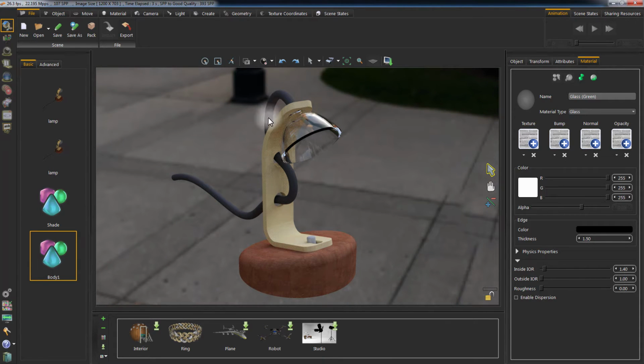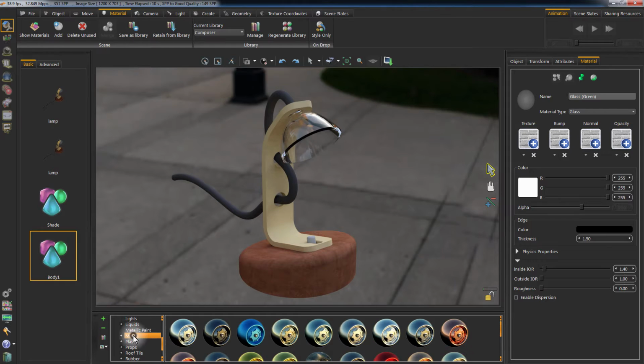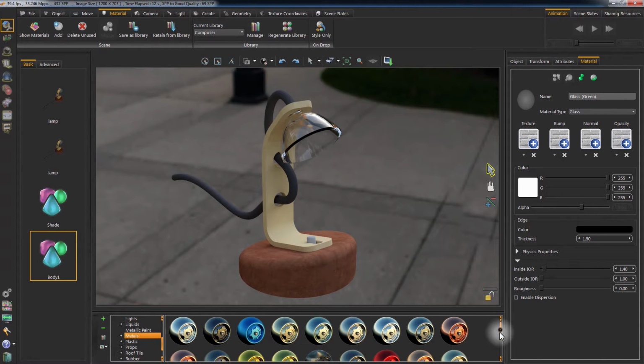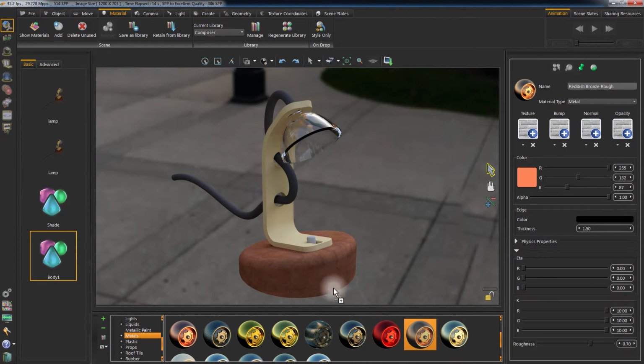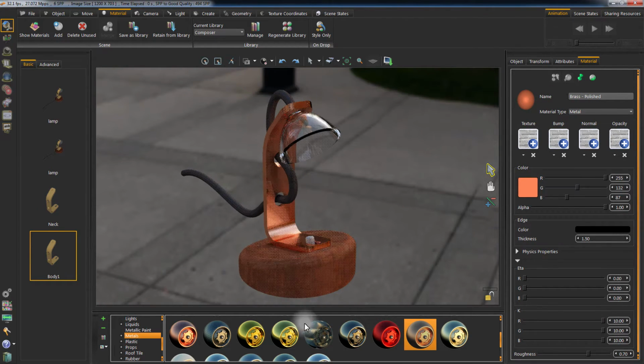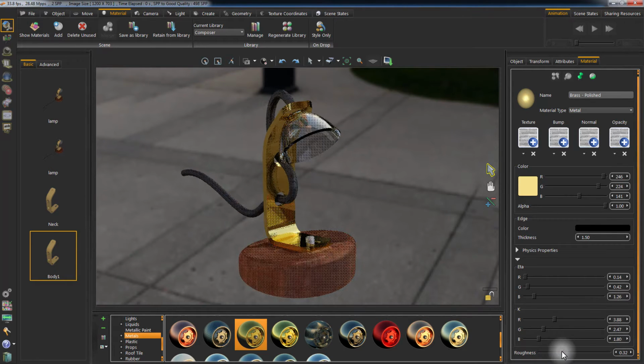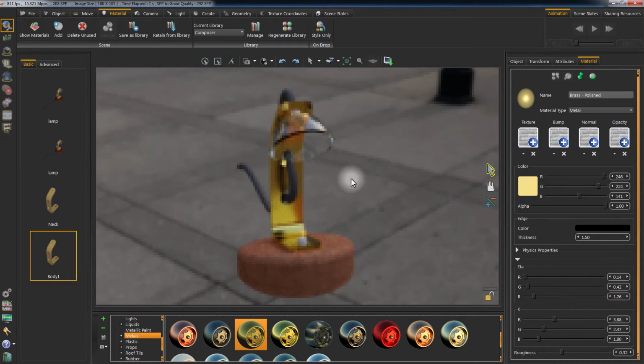Go to the Material tab in SimLab Composer to access the Materials library. Drag any material from the library and drop it on an object to apply the new material to all the objects sharing the old material. You can change the color or the attributes of the materials from the Material Attributes panel to the right, while the real-time rendering is still active.